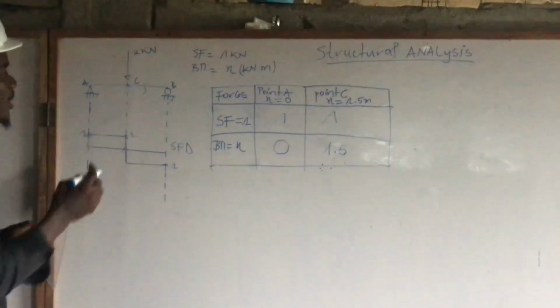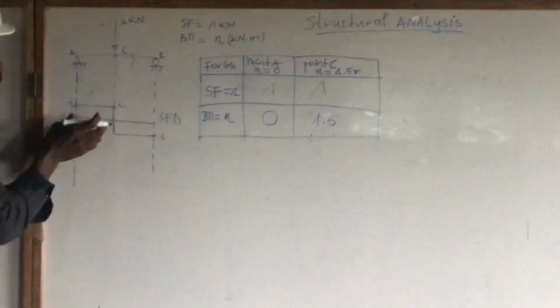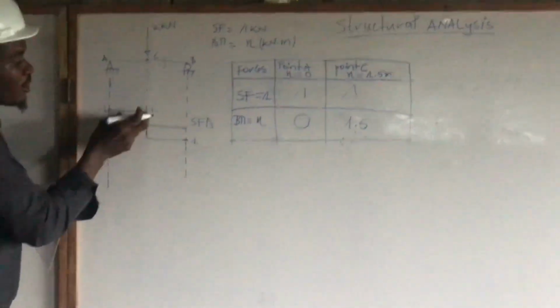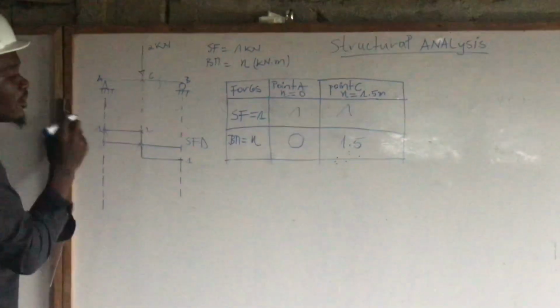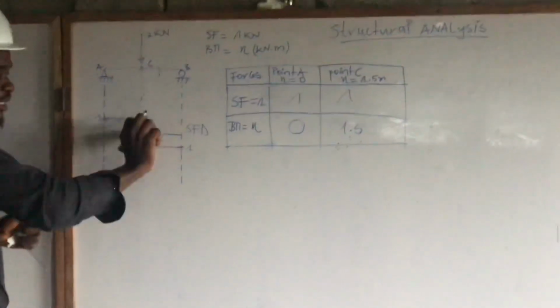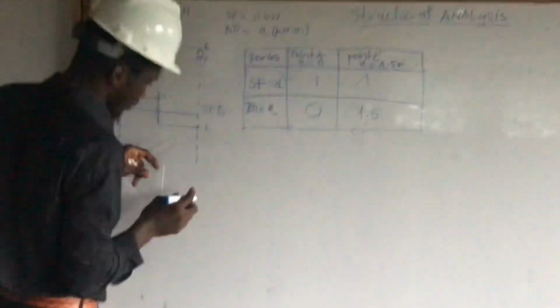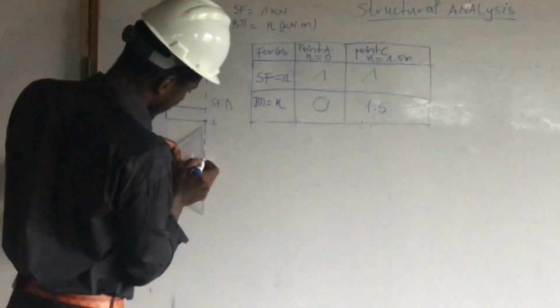That's why we say for a simply supported beam with a concentrated load, we don't need to make 2 cuts, because the behavior of the structure, which is this beam, will be the same on both sides, just that the other side will be the opposite of the other one in terms of magnitude, remember. Okay, so now